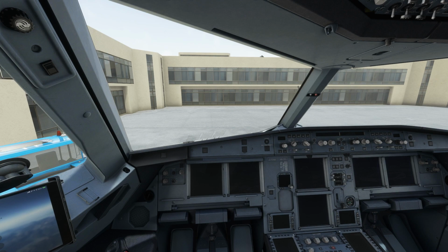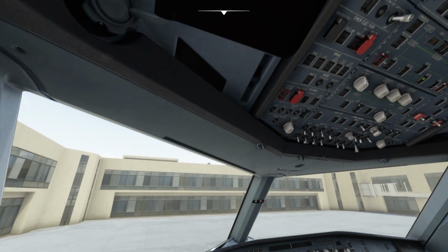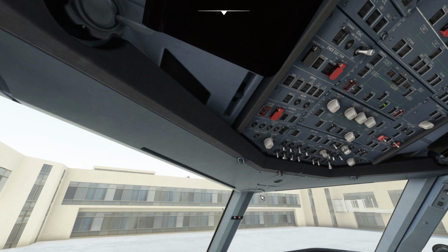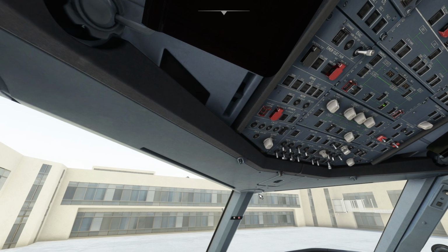So you have to turn on the auxiliary power unit, which is the APU, and you push back, and once the engines are started, you get the power from the engines and you turn off the APU. This is the procedure you have to follow, but just to start the plane, you need batteries, just like cars. For the initial startup, your batteries are switched on, you get all the lights and everything, and then you start the engine.